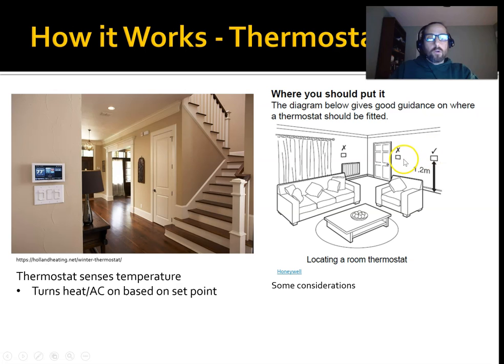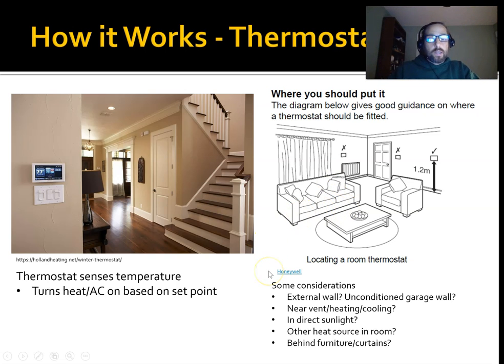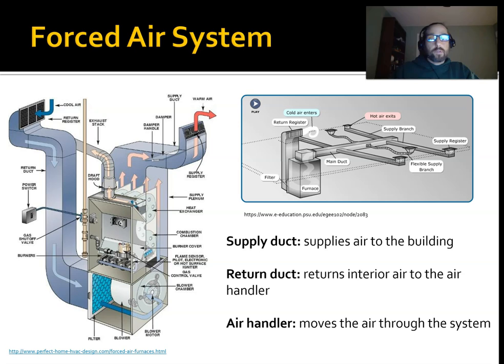You also don't want it sitting where it gets direct sunlight from a window, because again, that'll heat it up. You don't want it on an exterior wall. You don't want it next to the door. And this one is a radiator, so you don't want it next to something blowing warm or cold air on it, because that'll mess the whole thing up. Okay, so that is important, and it may pop up when you're on an energy audit, so you want to look at thermostat placement. Generally speaking, most of the time these are installed properly, but it is worth considering.